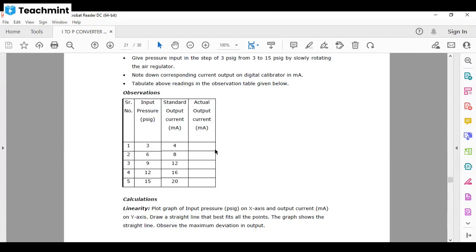live zero. If an instrument has zero input and the output shows zero, we cannot understand whether the input is given or not. For this reason, the ammeter reading of 4 milliampere is called live zero. If the zero input gives zero output, then this is the dead zero or dead zone. And if the zero input shows 4 on the milliampere meter, then it is the live zero.